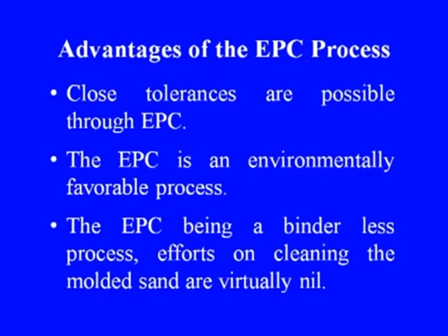The EPC is an environmentally favorable process. The EPC being a binderless process, efforts on cleaning the molded sand are virtually nil. The EPC process is viewed as a value added process rather than a substitute for sand casting. The EPC is cheaper and much simpler than the investment casting process, as the foam is more readily available and cheaper as compared to wax.